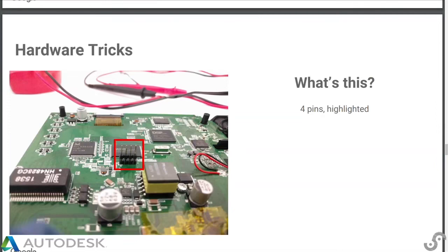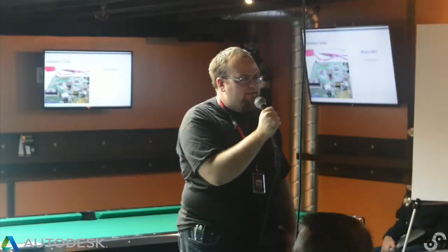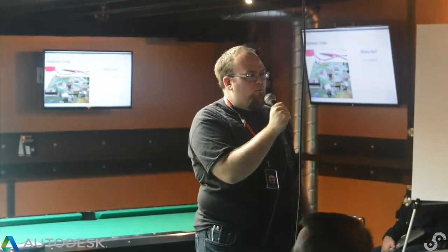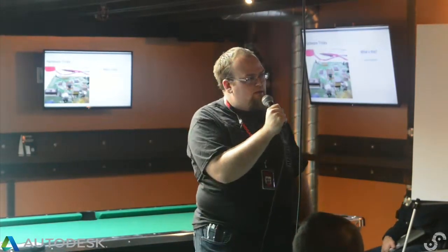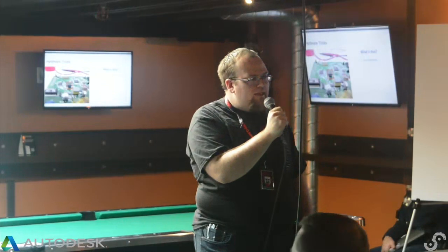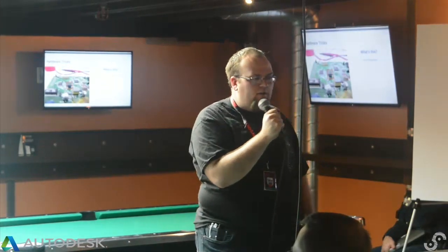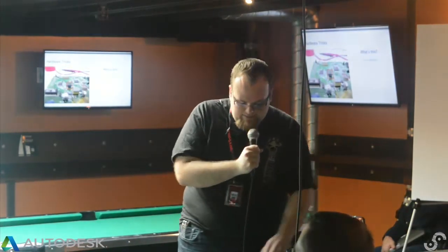So let's talk a little bit about the most basic hardware tricks, right? This particular one was actually super straightforward because on the board there are these 4 pins sticking out of there. So how many of you have actually used a serial port in your life? Oh wow, that's actually more than I expected. There's a lot of people, even in this industry, that I say serial port and they go, what? So a serial port normally has like 9 pins on it, but it turns out you really only need 3 pins to communicate. All you need is ground, TX, and RX.